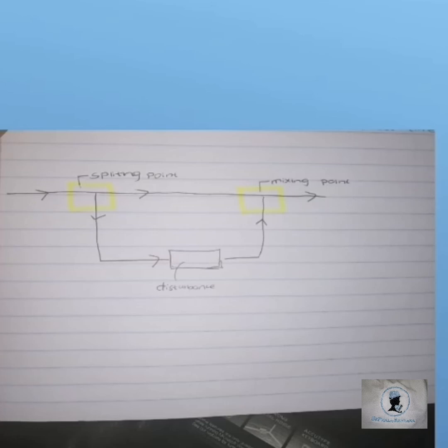But if we take a sample from the bottle and a sample from the glass, and take them to a laboratory to test whether the concentration changed, you will see that the concentration of the Oros in the glass and the concentration of the Oros in the bottle are the same. So this is why at a splitting point, concentration does not change. Only the flow rate changes. And then we go on.